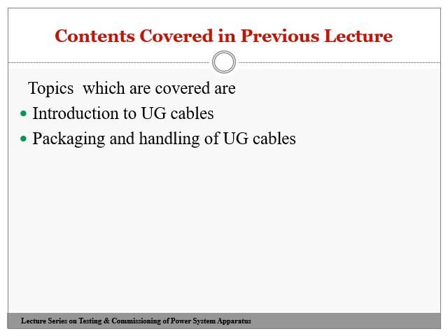Once the cable comes to the installation area, storage becomes important. If you are going to install immediately, no storage is required. If you are installing the cable two or three months after receiving it, you have to make elaborate storage arrangements so that the cable is protected properly, without moisture entering from either end.